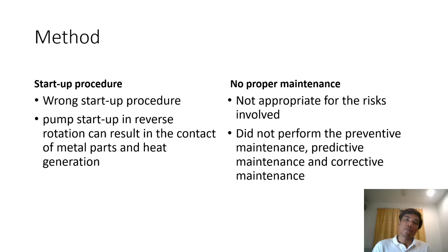Next on the cause of method, wrong startup procedure. As an example, pump startup in a reverse rotation can result in the contact of metal parts and heat generation. No proper maintenance appropriate for the risk involved. Did not perform the preventive maintenance, predictive maintenance, and corrective maintenance.